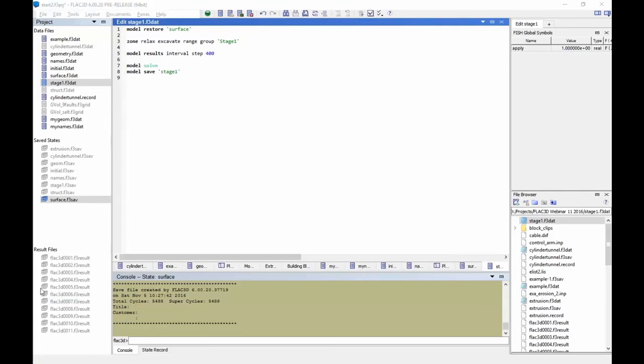Okay, there's been a question. Does the apply command assign stress to the face, which is inside to the axis? Can you read the bottom question there? Yes. Does the apply command can assign stress to the face? Yes. It doesn't matter if you apply normal stress. It doesn't matter what the orientation of the face is. It will be applied normally.